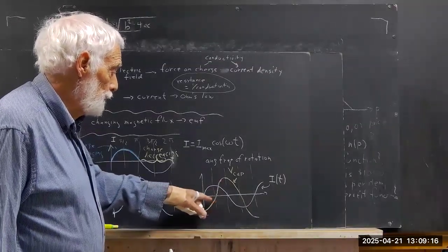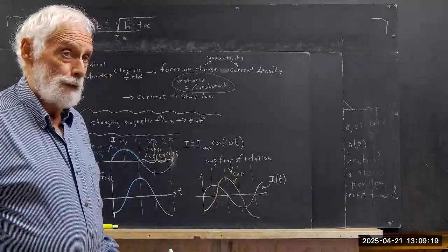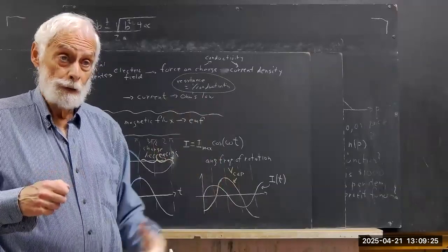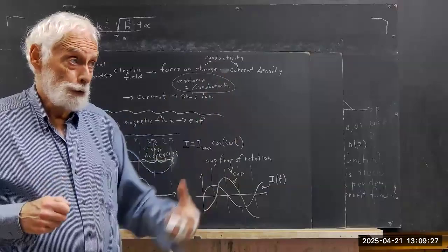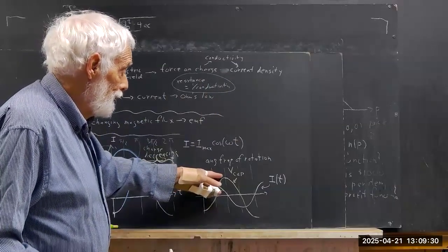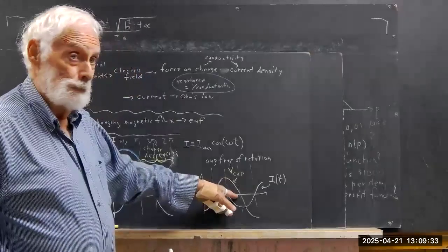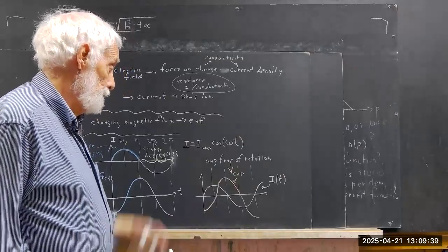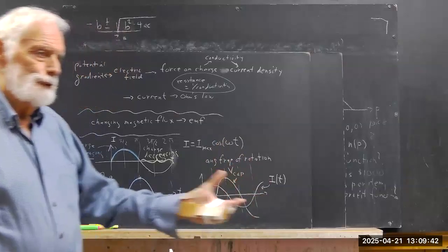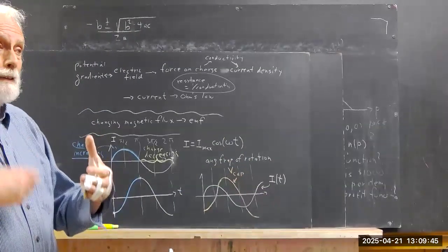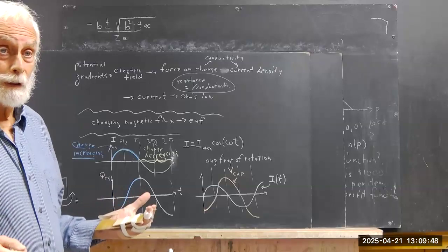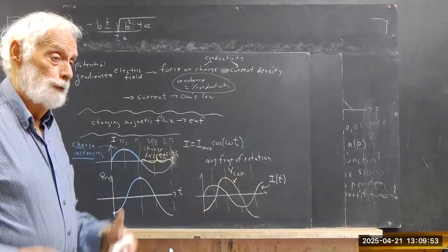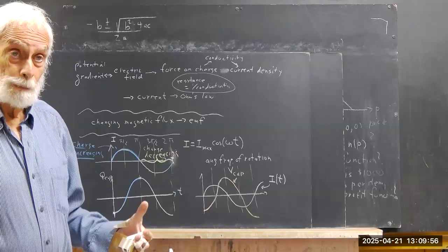The voltage in the capacitor is always 90 degrees behind this because, again, when you first reverse it, the capacitor still has charge on it. It still has its voltage. And that voltage doesn't decrease to zero until a quarter of a cycle. Reconcile that with your tactile experience. So you know what it feels like. You'll understand this much better if you relate what it feels like to what's going on.